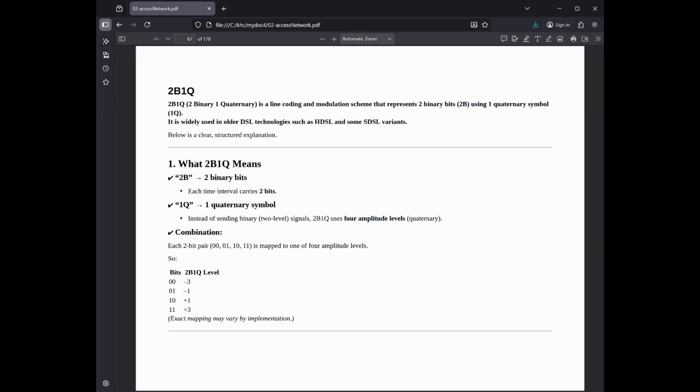1. 2B1Q doubles this efficiency by grouping bits into pairs, called dibits, and mapping them to one of 4 specific voltage levels. The standard mapping, using gray coding to minimize errors, is typically: dibit 10, quaternary symbol +3, +2.5 V; 11, +1, +0.833 V; 01, -1, -0.833 V; 00, -3, -2.5 V.